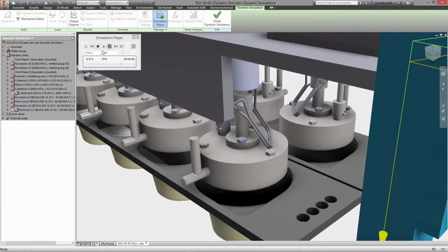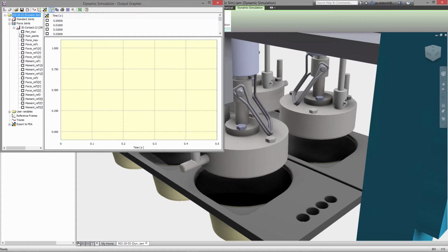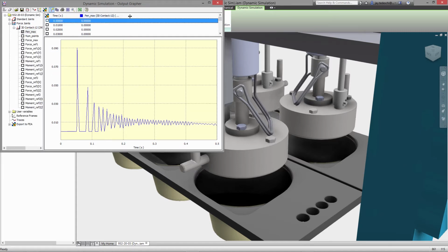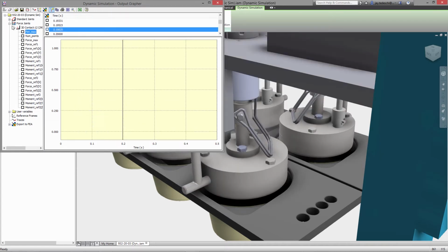This second scenario is especially powerful, as you can transfer calculated forces into the stress analysis environment to evaluate the performance of critical components in the design. Setting this type of study up is simple. Just describe the motion of the joints that control how the product operates.